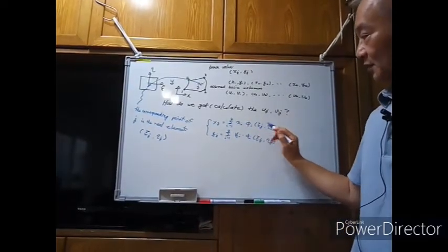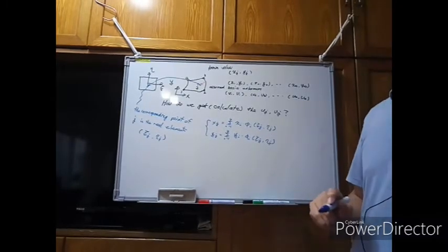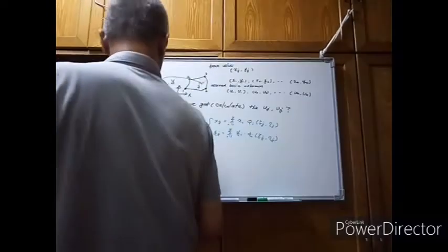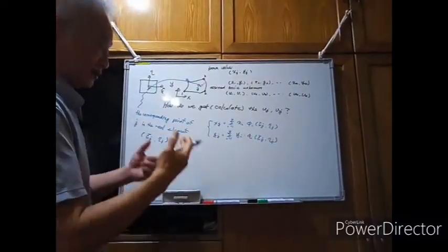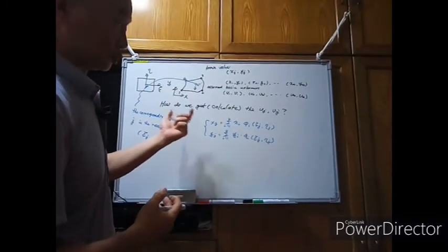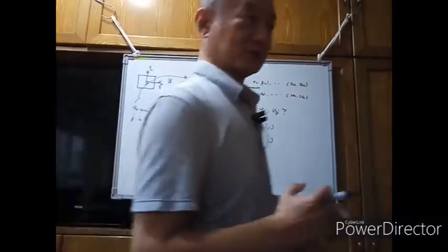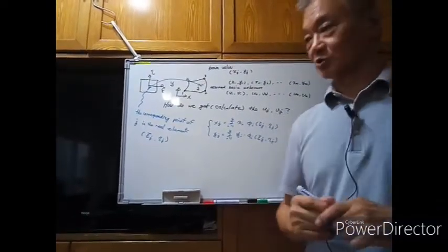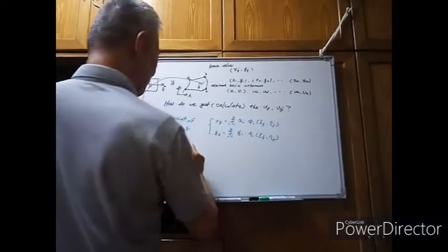Okay, but how can we get the xi J and the eta J? Sometimes for relatively simple functions, for example, if you consider the 4-node element, sometimes you can solve the inverse functions.